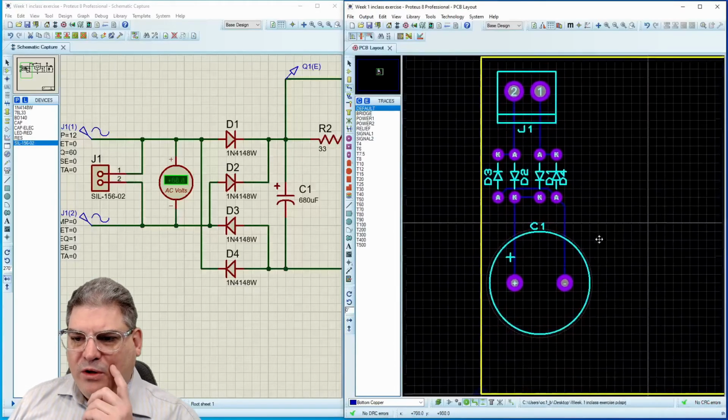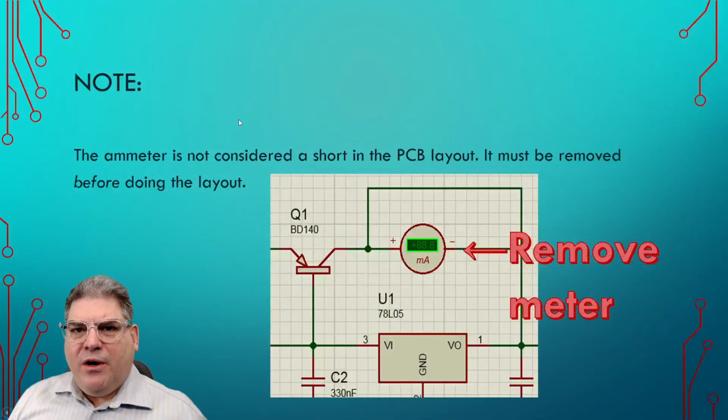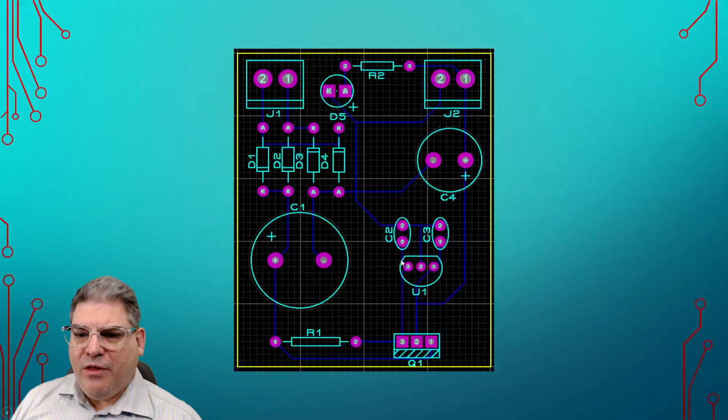This is relatively simple. Okay, one thing that I mentioned earlier, and just to reiterate, is that if you did put in a current meter somewhere that is in the current path, putting a short around it will cause a problem when you go to simulate it. Not putting a shunt around it when you go to do the PCB layout will cause a problem. Basically, this will be an open circuit, so make sure you deal with that.